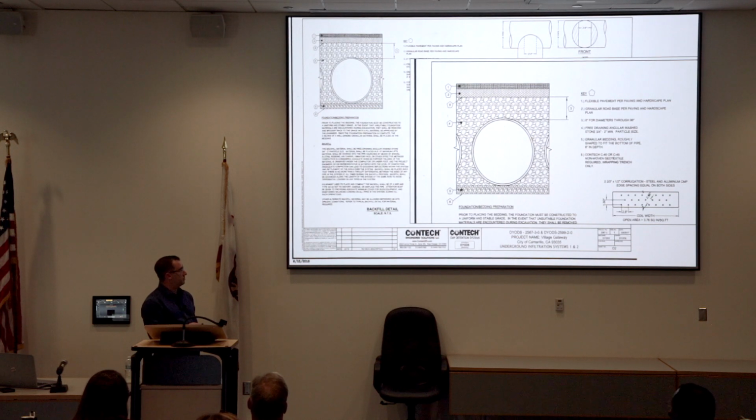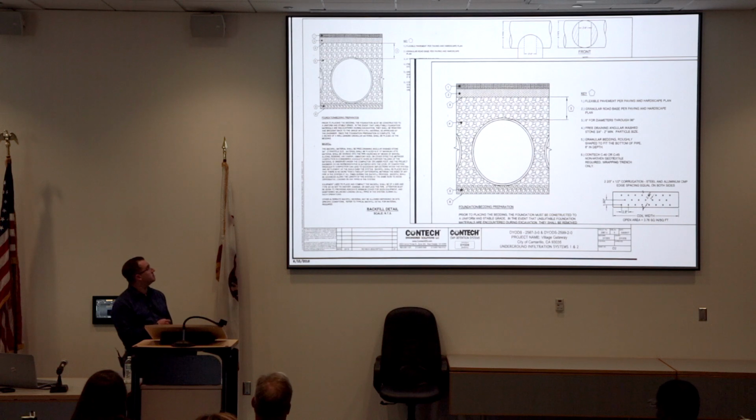There's not going to be real easy ways to design that. Ultimately, the engineer should have used a different cut sheet, should have used one that didn't have this fabric, because the fabric's useful in some circumstances, but not for what he was trying to use it for. He was trying to infiltrate and get the fines out within the system, but he was going to trap them in.